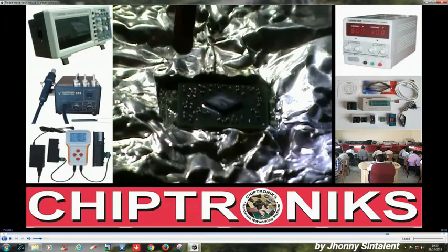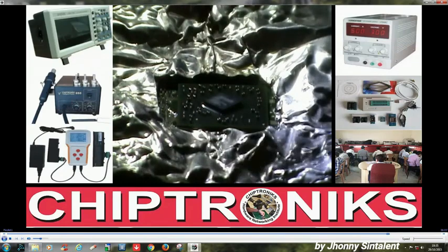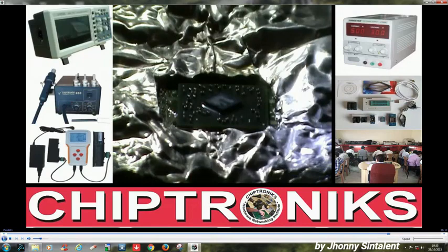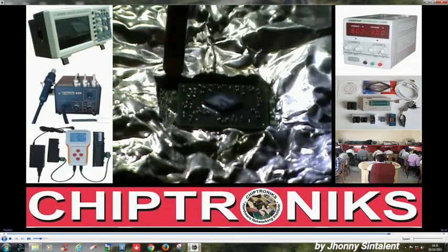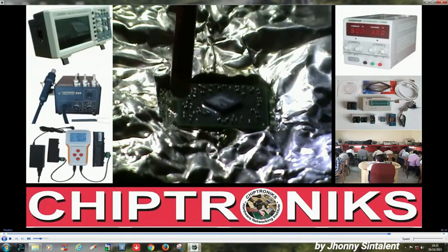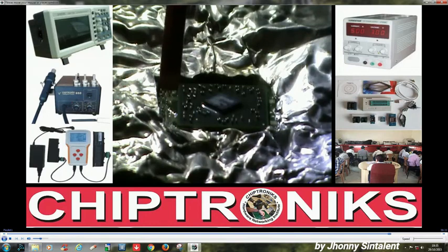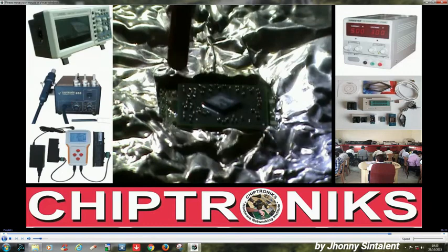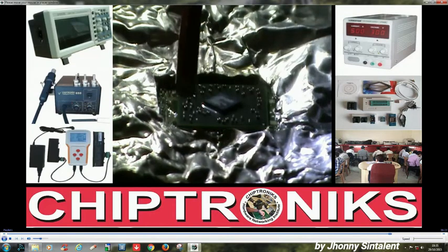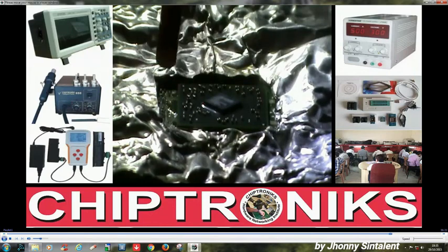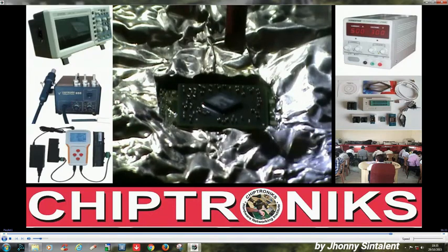Also there is a marking on the BGA chip as well as on the PCB, which shows which way to orient the BGA chip. Sometimes there is confusion about how to orient the BGA chip, and we can clear this confusion by seeing the small marking on the PCB. Both the markings should be in the same direction. That is the way to orient the BGA chip.